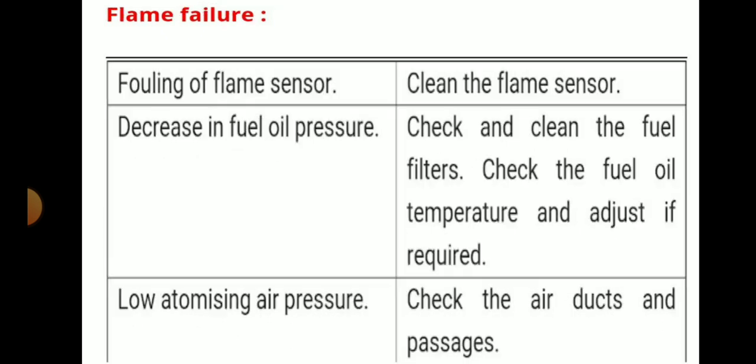Okay, flame failure. Flame failure may be due to fouling of the flame sensor, decrease in fuel oil pressure, or low atomizing air pressure. For fouling of the flame sensor, you can clean the flame sensor.